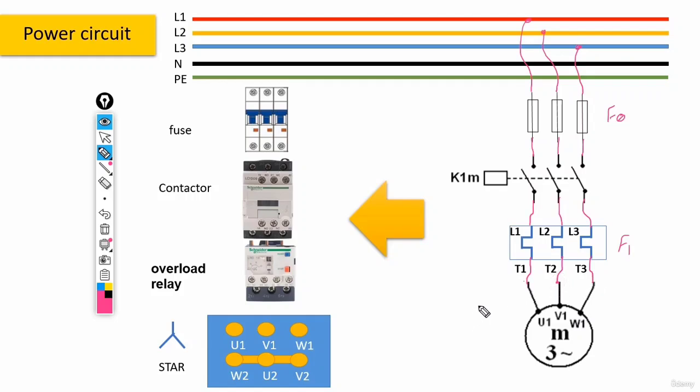All right. Now, let's go through the realistic view. Now, what we were supposed to do, that's right. First, connect the phase lines to the fuse. Here we go. Oh, and by the way, guys, the fuse could actually be any type. Now, anyway, fuse to the contactor.